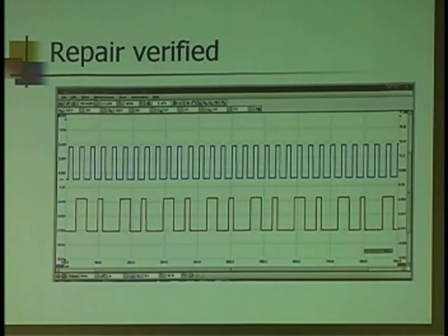Floating ground is held above vehicle ground. Okay, and that's to prevent interference, right? So if you're checking something that's grounded to the module, then it's going to have a floating ground, and you may see as much as, what, 0.7 as a reading. If you're not aware of that, you may go like, ooh.